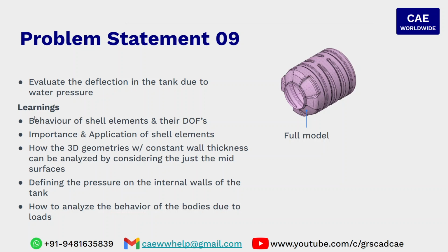The learnings by solving this problem are the behavior of shell elements and their degrees of freedom. Shell element is one of the key elements used in finite element analysis to capture the behavior of thin-walled, uniformly thick components very accurately. The importance and application of the shell elements, and how 3D geometries with a constant wall thickness can be analyzed by considering just the mid-surface.